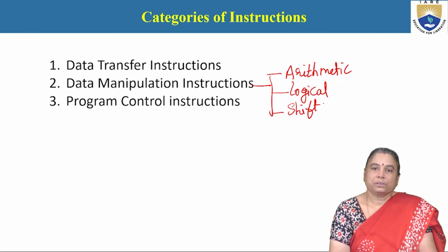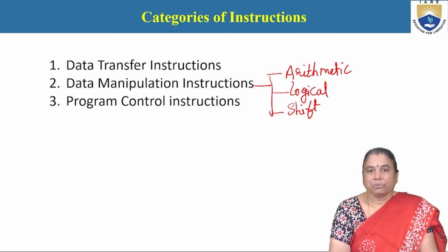The shift instructions are generally used for serial data transmission. There are three types of shifts available: logical shift, arithmetic shift, circular shift. Under these varieties, again two types are there: left shift operation and right shift operation. To support these operations, the mnemonics that can be used are ROR, ROL, SHL, SHR, etc.